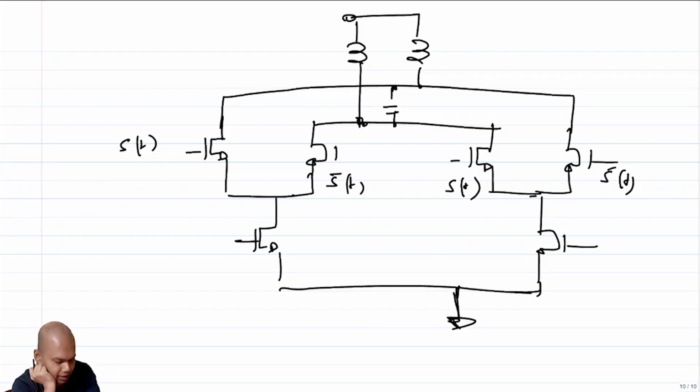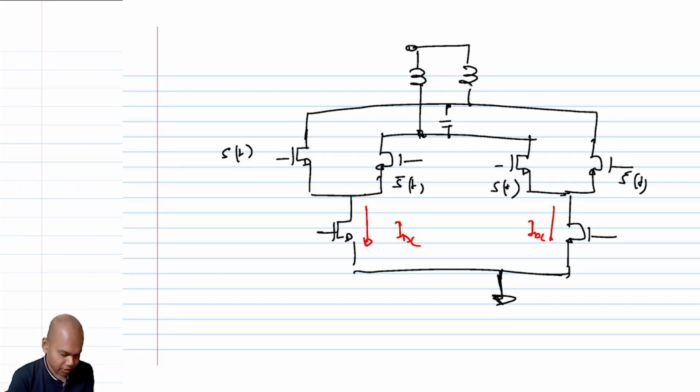But one might say that if this always gives me gain, why don't we use this? There is always a story behind why something is not always useful, and the reason behind this is a special kind of noise that is called flicker noise. So we have not talked about flicker noise at all. So let me give you a 2-minute primer of what flicker noise is.